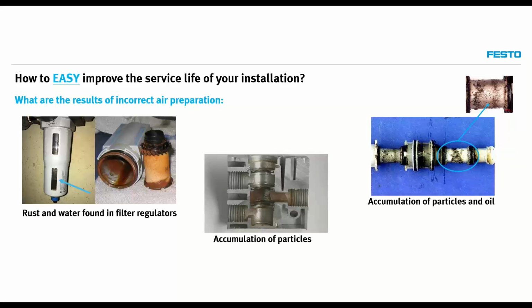We as Festo always use a grease instead of an oil. So this should not be here. This impacts the function of the valve and the life cycle of the facility. So what does it result in? It results in unplanned standstills of your equipment, or less reliability.